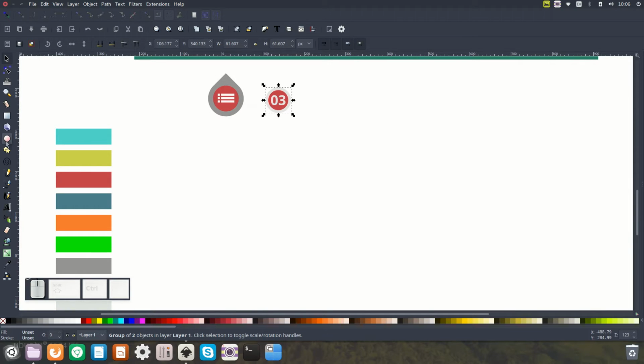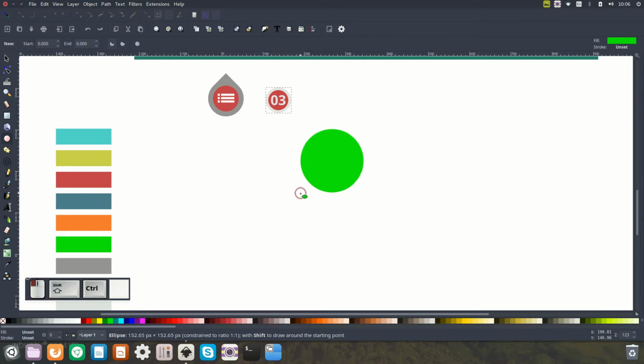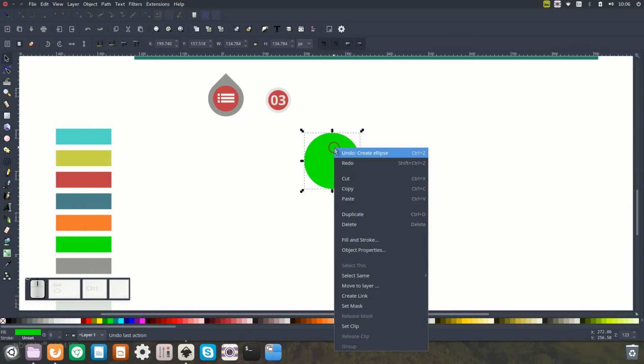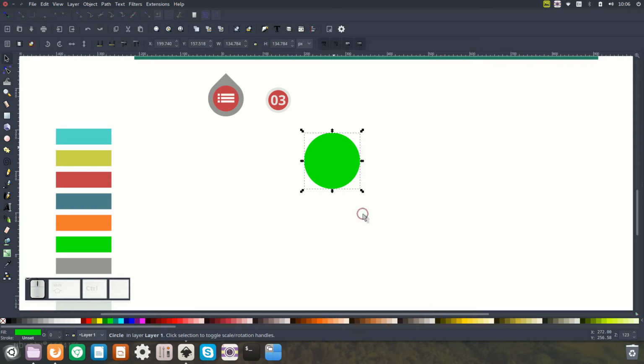So to do this, let me click on a circle, hold shift and control, slightly drag and finish this. And similarly we'll right click on this one and then duplicate this and change its color to probably red here. And then with this selected, press shift and control and slightly click on this arrow here, and then slightly take it in. As you can see, we got this nice looking icon here. Now we have the circle which was below here, and the top, the red one.